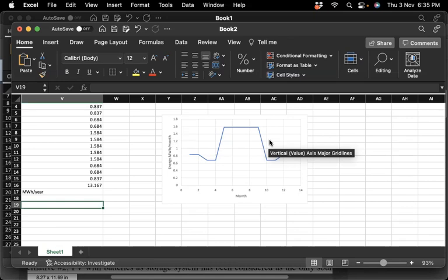However, if it's a PV standalone system without any diesel or any other source, and you don't want your load to be off at any time, then you have to consider what's called the worst case scenario model. So your decision depends on the circumstances or the conditions of the load, if the load is critical or not. And here we can have different types of loads. For example, we have what's called summer loads, like what you are seeing now.